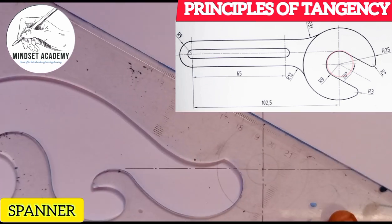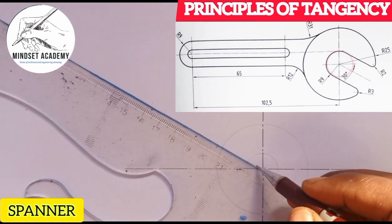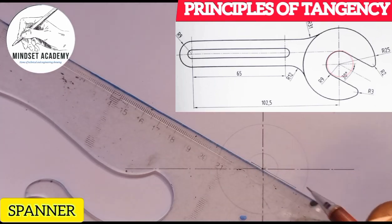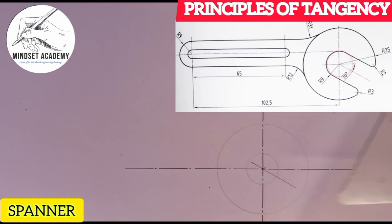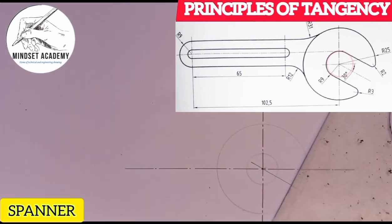If I move it to this point here and draw a line this way, that line is 30 degrees. And I'll draw another line to counter it, 60 degrees this way. When it's placed this way, this is 60 degrees, the longer side of the set square.